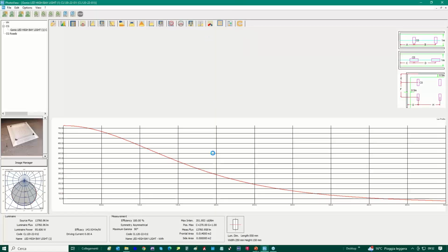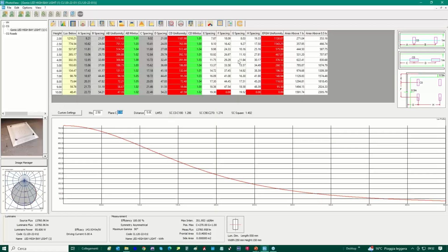Next, the analysis. Usually this diagram, this table, is used for emergency lighting, and in function of the different configurations of the luminaires we have here, we can come through this table to analyze whether, for example, the minimum lux is achieved using this luminaire, and whether the uniformity is achieved or not.